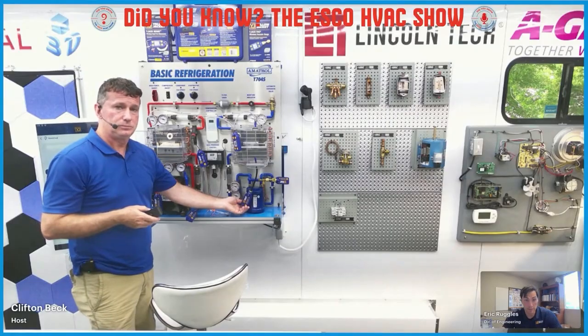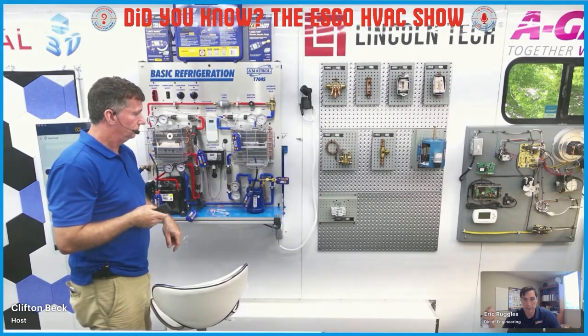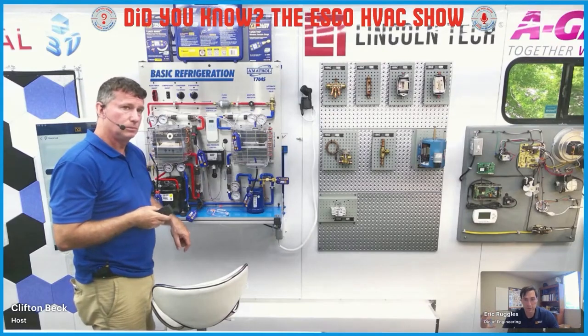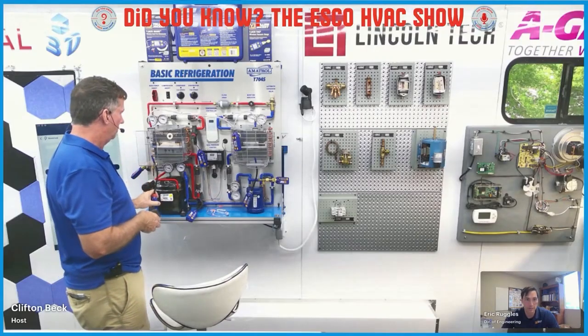So that's your psychrometer. That's going to the air side. It's got a long probe, 12 probe on it, and you're going to want to put that in your supply and return air streams so you can get your dry bulb, wet bulb, relative humidity, and dew point of your airs. So we can compare those, get the enthalpies, and actually determine what the capacity is of the system and what efficiency it's running at.